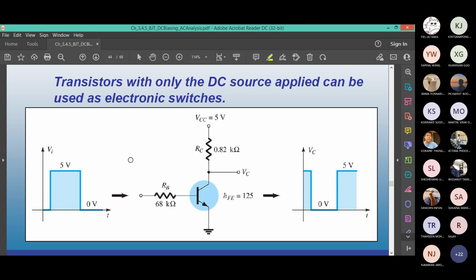We can analyze this circuit as well. Let's say the input signal, Vi, is applied here. Input is not VCC, remember. The signal is here, there will be a capacitor and so on. Now, we are talking about DC, so there is no capacitor. VCC is not an input. VCC is the biasing that you need to turn on the amplifier. Without VCC, the amplifier does not do power transfer.